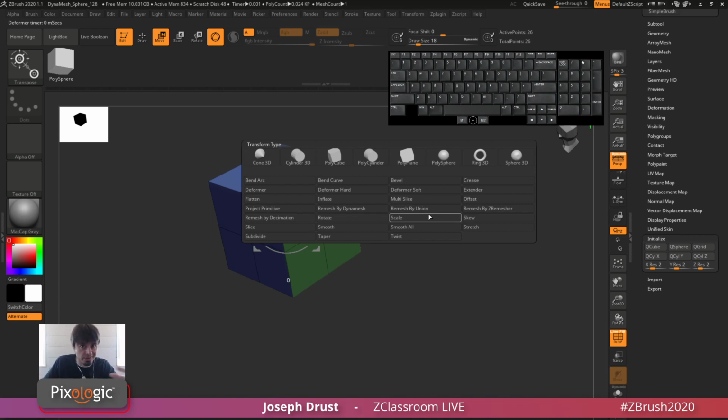Now it's not going to apply any extraction functionality or subtraction functionality to your mesh. It's only going to take your model and use the Boolean to take any of that intersecting geometry and weld it together. You should be able to use it on low poly meshes. It may not give you the triangulation you want, because if it's really low, anywhere where parts intersect with the live Boolean, it's going to generate triangles at that area.